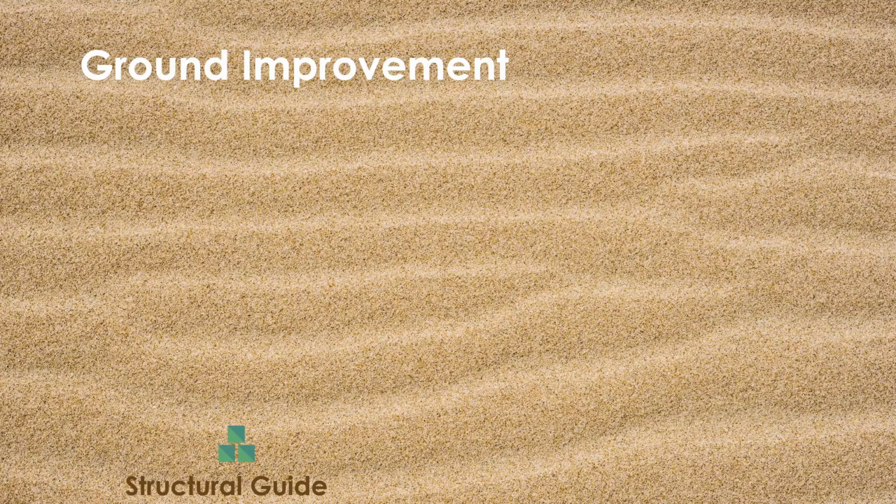Ground improvements. Why we need ground improvements? What are the methods available for ground improvements? Vibro compaction, vacuum consolidation, preloading, Vibro replacement stone columns, grouting, improvement by admixtures, dynamic compaction of soil. All those will be discussed today.